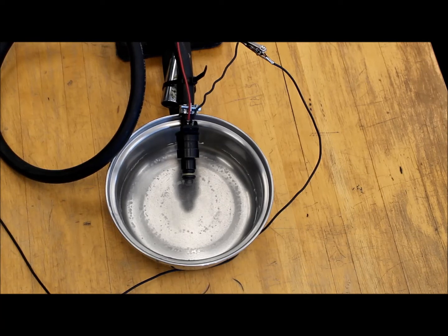Years ago, a lot of vehicles had injectors mounted outside of the intake manifold, throttle body injection. But the concept is the same. The injector is a liquid control solenoid. When it's energized, it's a normally closed solenoid, so when it's energized, like so, it begins to flow, and when you take the power away, it shuts, and there's no more flow.